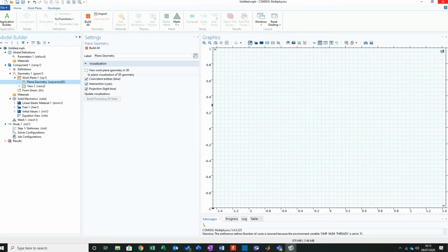Now what we're going to do is model each line representation. Then once we've created each line representation, we're going to create a 360-degree rotation to give us the dumbbell design. Because as we know, if you look at half of that profile and how it's been executed, the best way to do it is the side profile and revolve around it. We will use that to our advantage. By using this, it does minimize the computational need of the system and makes it far more efficient.